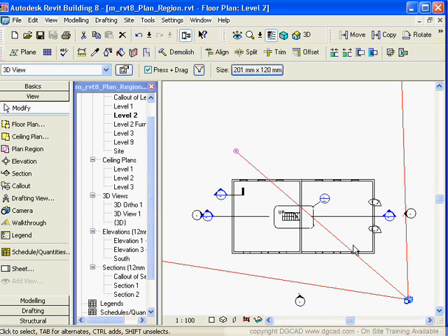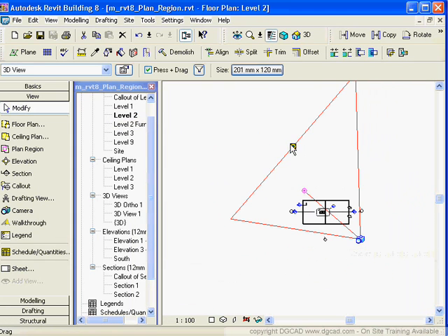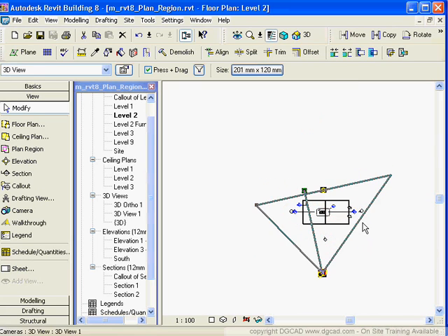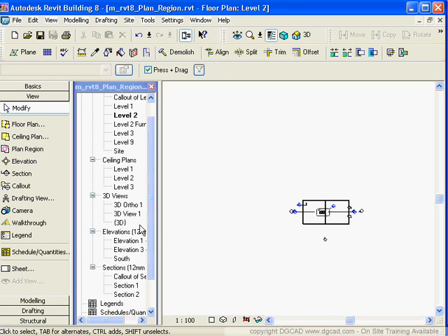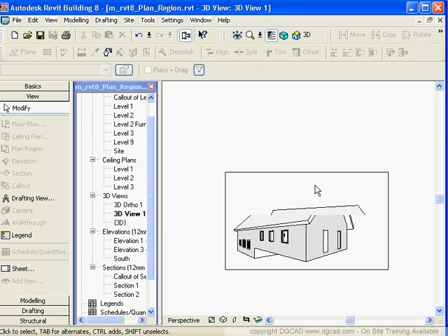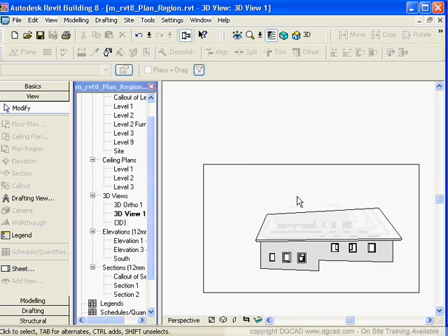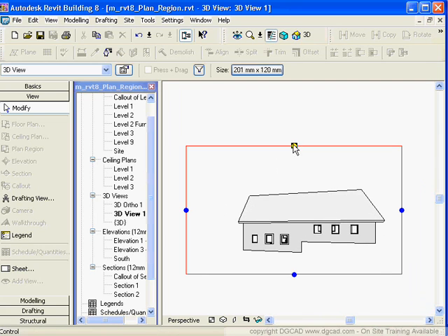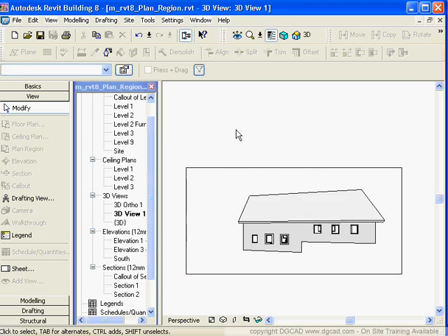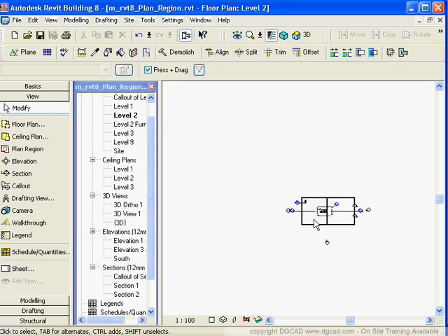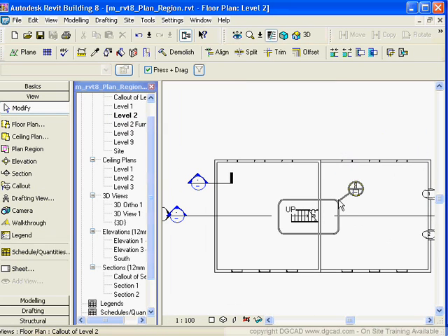Once inside of there, if you want to go back to that camera view, you right click on here and say show camera, and then on your plan views it's going to show you where that camera is. And then we can grab this and start to manipulate this around as we please, double clicking on it. Oh, back to here. Zoom in for my graphics a little bit, so a bit of a wide angle on that. Okay, so we can go in and create cameras with our view.